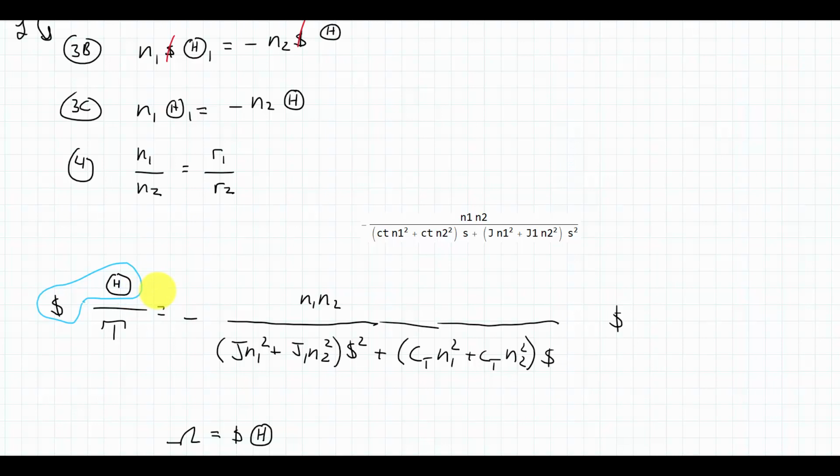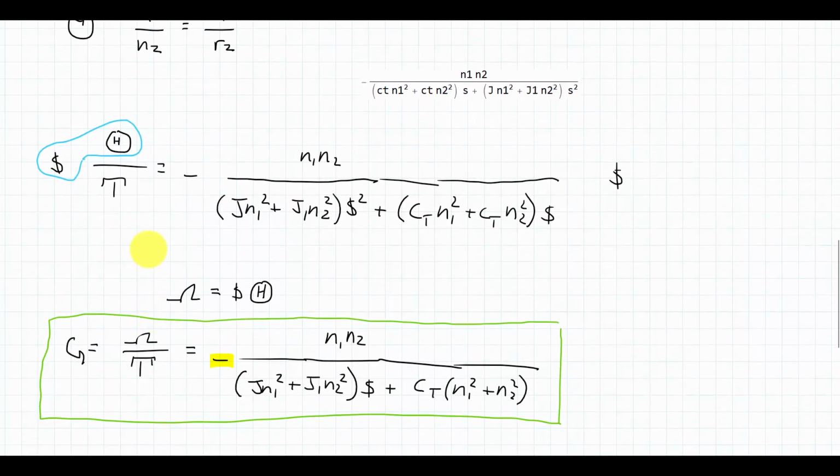But I can start here, and it's going to be pretty easy to go to the next step, because in the Laplace frequency domain, multiplying by an s is equivalent to taking a derivative in the time domain. So, taking this transfer function, multiplying the left side and the right side by s, I can rewrite s times big theta as capital omega, and that's where I needed to go. So ultimately, I was able to find omega over T then after multiplying by s, and we got the final transfer function for this problem.